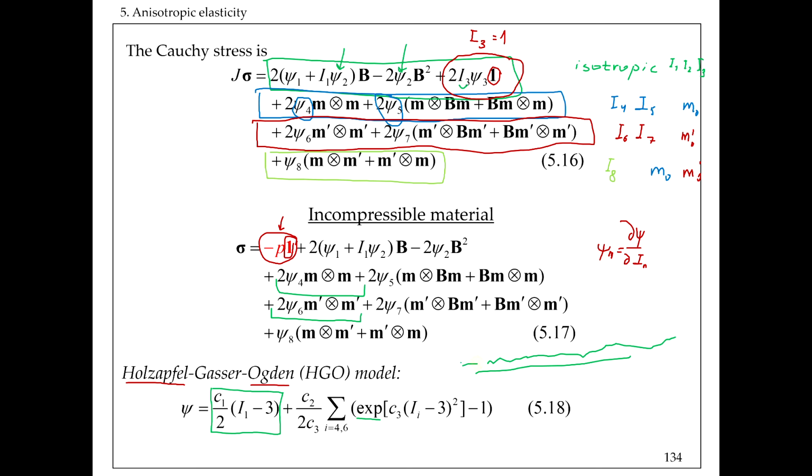Therefore when you apply tensile loadings, initially there will be a range of deformation where they are not straightened, and so they don't really contribute much to the tensile strength of the material, to the tensile stiffness of the response. But then gradually as they straighten with deformation, they start to strongly show their reinforcement to the matrix, and these exponent functions allow capturing that very nicely.